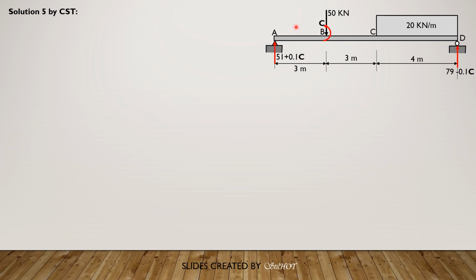So same sectioning as before. And at C also, same sectioning. So we have EI theta B is equal to summation integral 0 to L of moment, partial of moment with respect to the couple, then dx over EI. Then for delta, or deflection, the same, but we have integral 0 to L, M, partial of that moment with respect to the load P, then over EI.